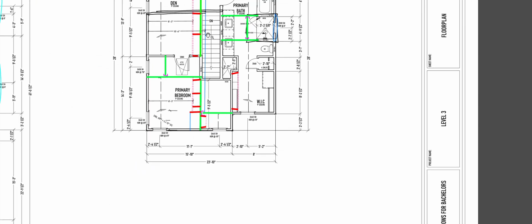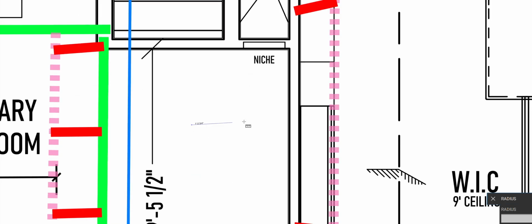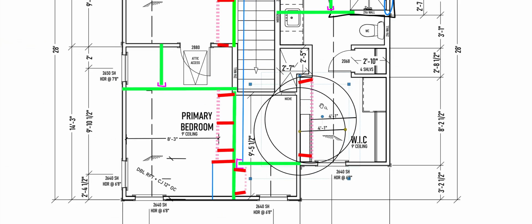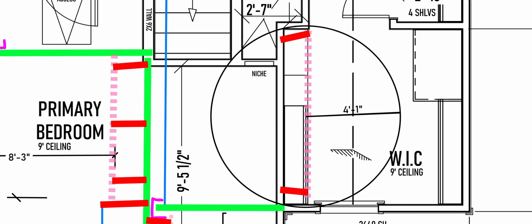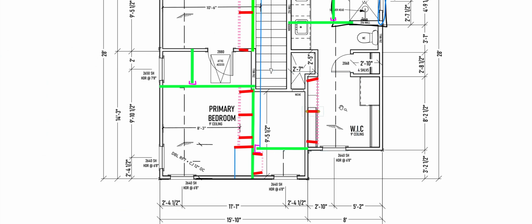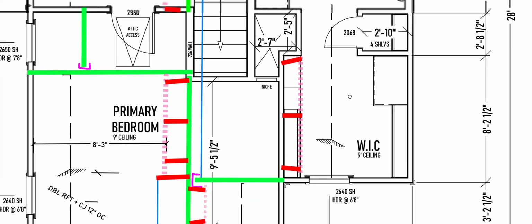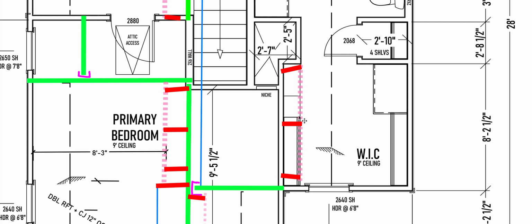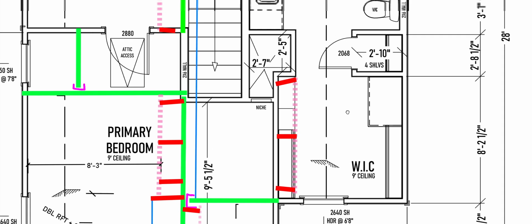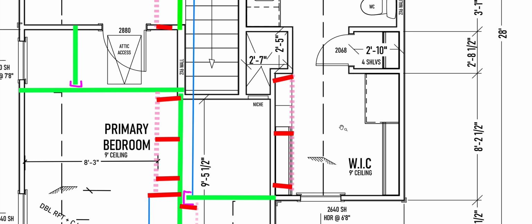and then look at the spacing. I probably deleted my circle, didn't I? And then I want to look at the spacing here. Okay, one brace in the middle would be plenty here, so I'll do that. Okay, so what I did here is I added a purlin support as close as I could to this, and I set that weight down on this wall so I know that everything's happy hunky-dory in here. There's no crazy problems.